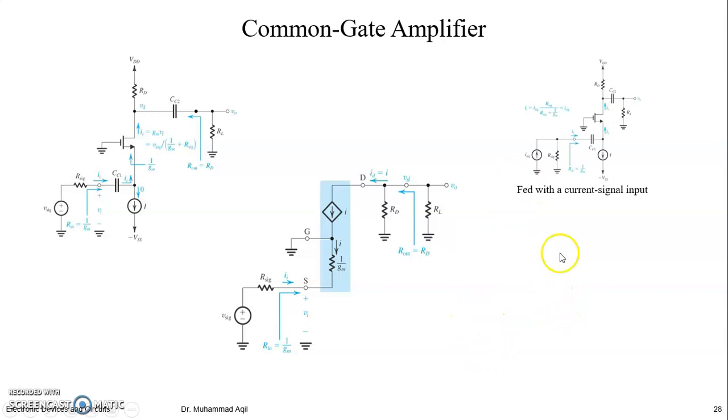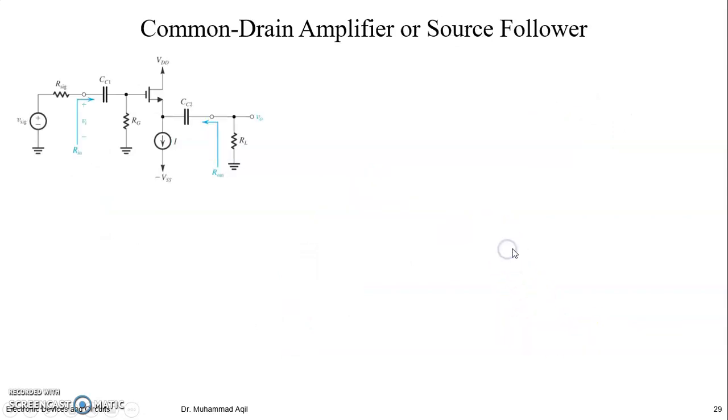So please do it yourself. Again, here they show a current source also. It will have the same relation, because for the AC equivalent circuit, this current source will be open circuited. You will finally have the equivalent circuit like this. Okay, so this is the common gate amplifier. This is the relation I told you we had found with a positive sign, right? We had found it already.